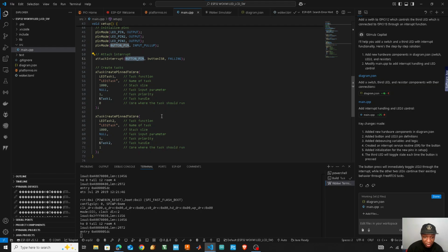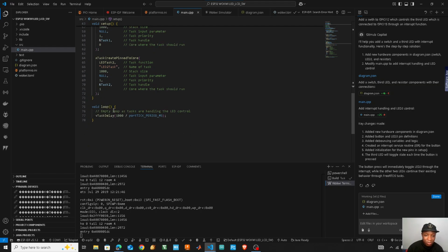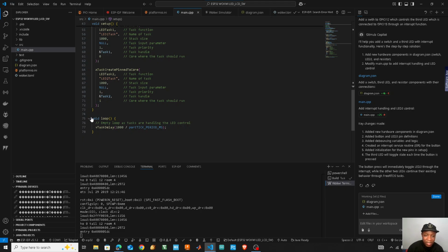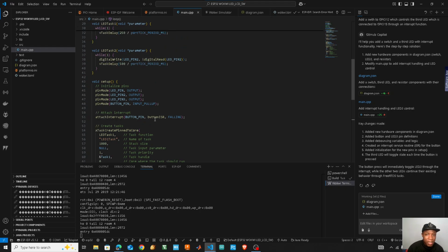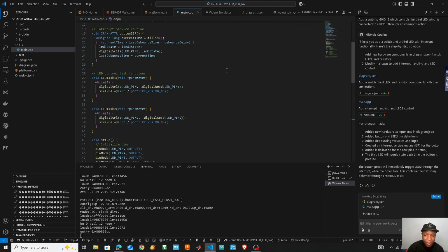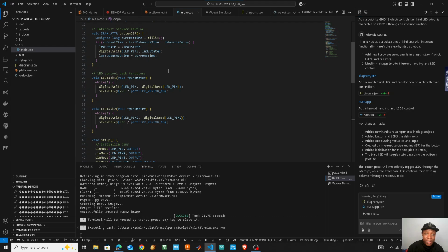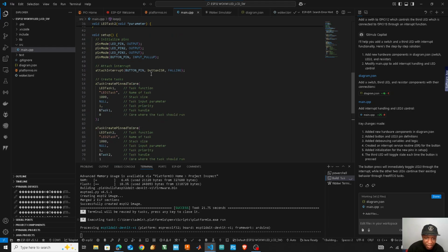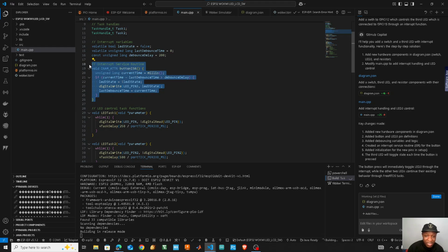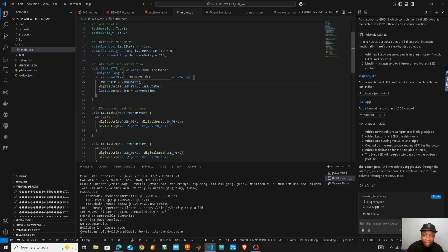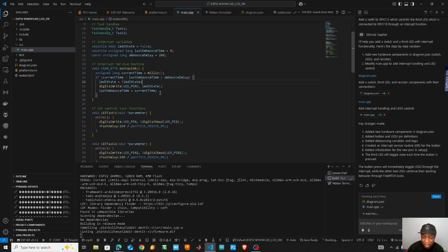Awesome. So we go and then we call these two tasks, which we had previously. And this function is not that much needed. You can remove it, but we just add this one to have this one looping inside here. Okay, so I think we're good. So let's build it. And one thing that we need to notice is, this interrupt service routine that we are making here, is it a toggle function, or is it a press and release function?